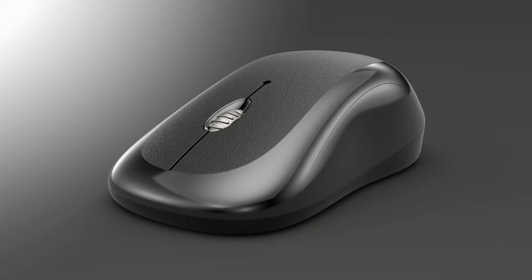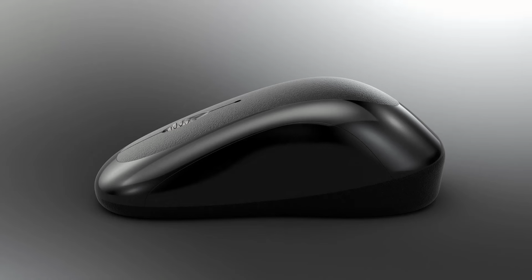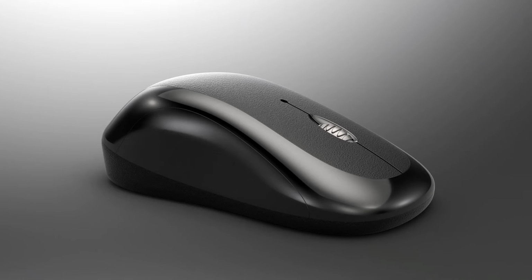The SubD workflow can be very useful for developing styling surfaces. Not just fast approximations, but good quality, well topologized surfaces that can be used for final data. In this model of a mouse, the majority of the shape was created as a SubD prior to being converted to NURBS, where it was then split into sections before adding the smaller details.